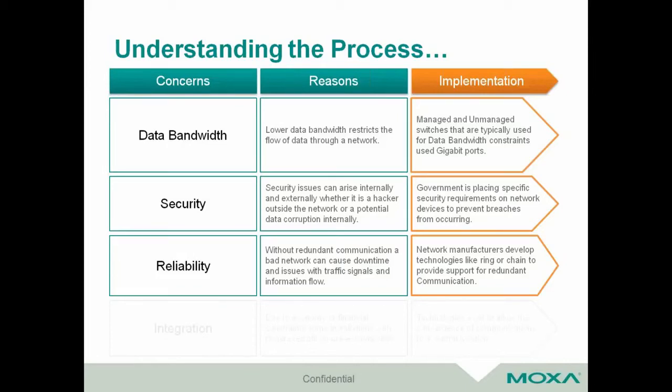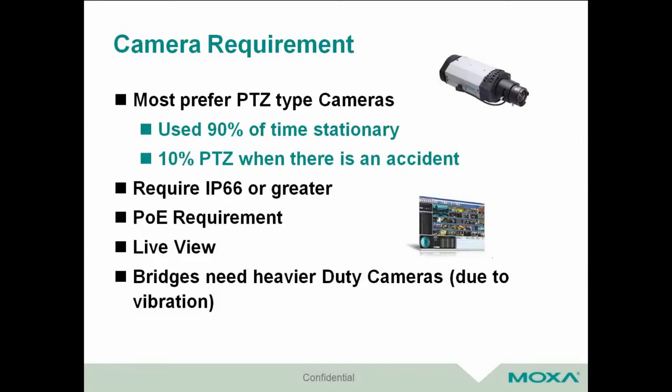Right now, I would say that a lot of camera vendors will have their own requirement for power. More specifically, DC and Ethernet cable is okay if you have that running, but a lot of the requirement for ITS is PoE. There's high power PoE, which isn't a standard yet. So different vendors will have different versions of their own high power PoE. Even though they mention it's 60 watts, some vendors will put two 30-watt modules in there just to support that 60. Or some of them will require devices actually outputting 60 watts.